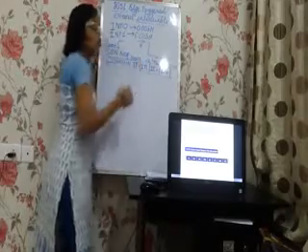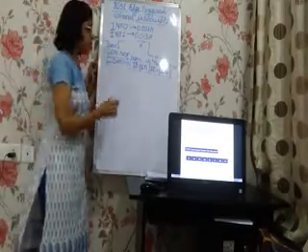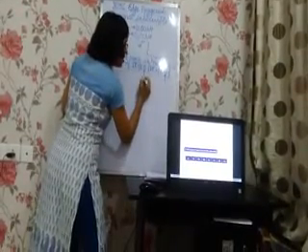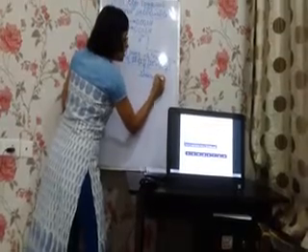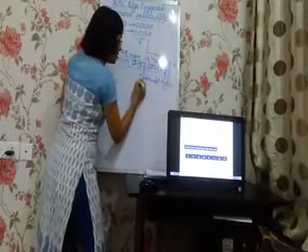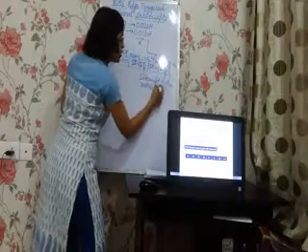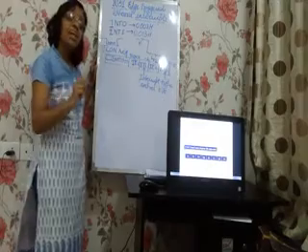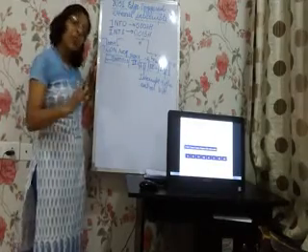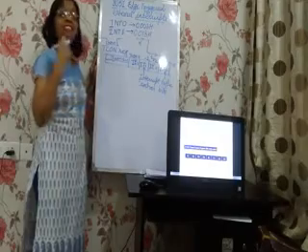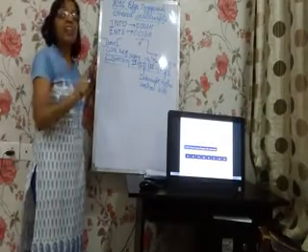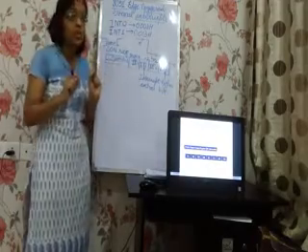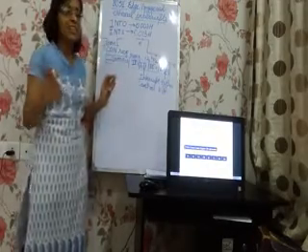Now what is the meaning of each of these bits? We'll talk about the IT bits. These are called interrupt type control bits. They tell us the type of triggering that we are going to give on the external hardware interrupts INT0 and INT1. So these are only for INT0 and INT1. For no other interrupt are these bits used.